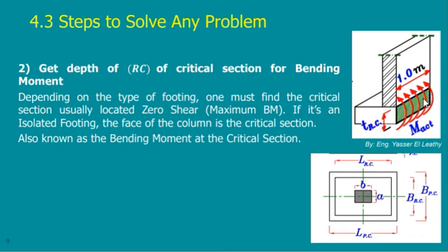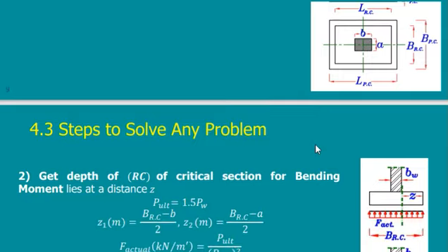But before we go into design, as a concrete section, there are some checks that we should do. It's not just depth and area of steel. There are some other checks. What are these checks? There is a check for something called shear and a check for punching. This you might have taken in structure, in reinforced concrete section designs.